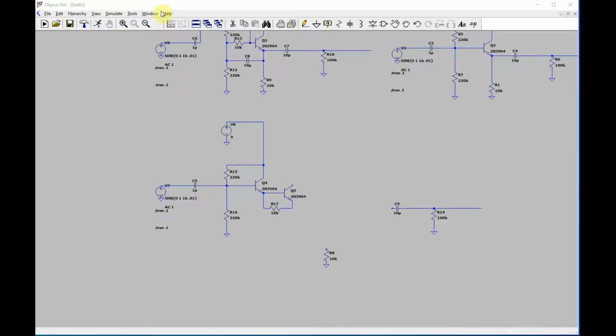So what you do is, let me just talk through this. The Darlington is basically, you get a low impedance output going into a high impedance input at this base with another low impedance output. So technically the HFE is supposed to be like the HFE of this times that. It's kind of like a super transistor or something. So this is usually a configuration.